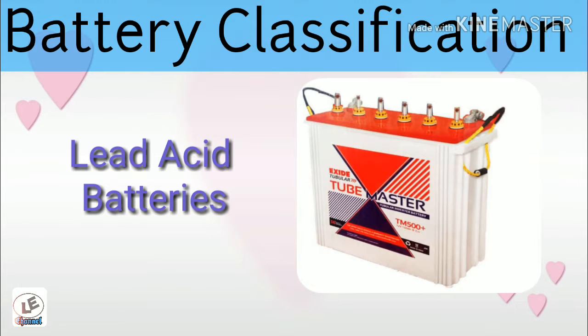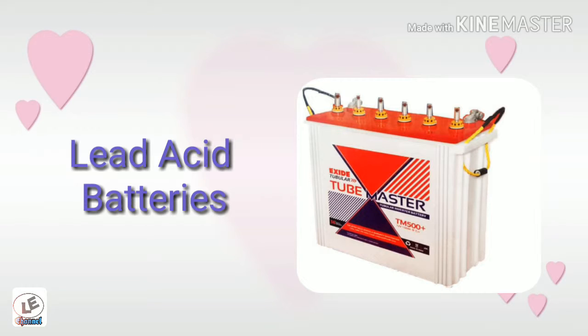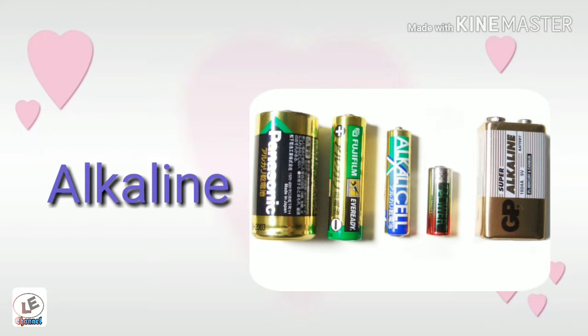Now different types of batteries. First one is lead acid batteries. They are used extensively in industry. They are very cheap, rechargeable and easily available. Where a lot of power is required and weight is not important, you can use these batteries. These batteries come 2 volt in a cell, and you can have extensions of 2 volt, 6 volt, 12 volt and 24 volts. Alkaline batteries are the most common batteries. They are one time use and they are available with a basic 1.5 volt cell and in sizes from coin cell to AAA or even D cells.